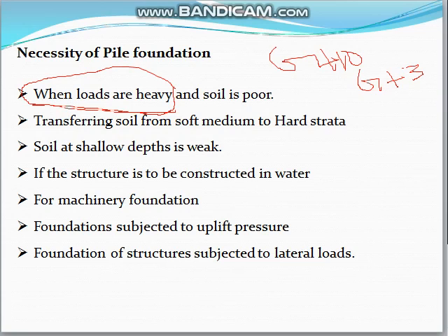In this high-rise building, definitely the loads are heavy, because if the floor number is increased, the load also increases, right? Due to the floor number increasing, the loads also increase. When the loads are very heavy and the soil is poor, generally if you find clay soil at a shallow depth, the soil is very poor. In these cases, definitely we have to go for pile foundation to get to the hard strata.